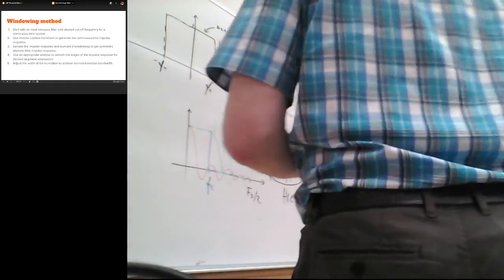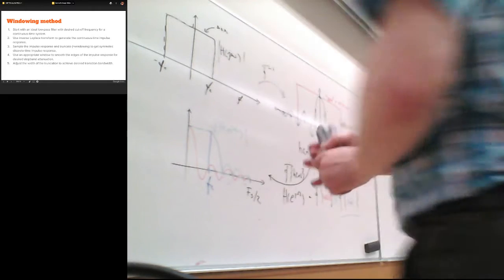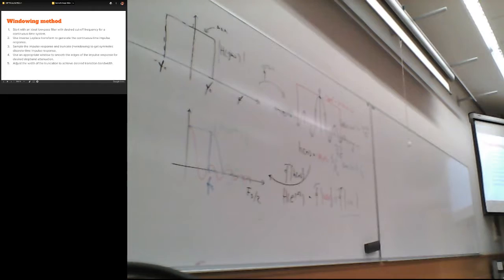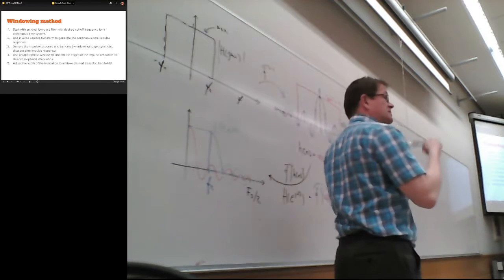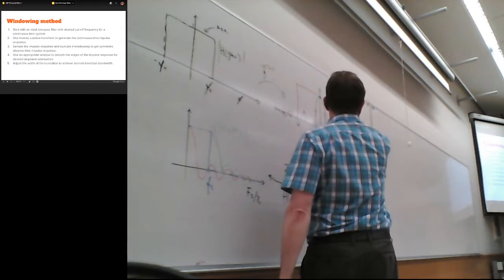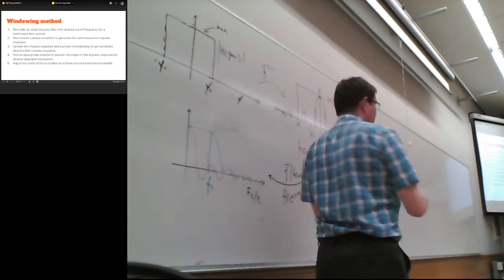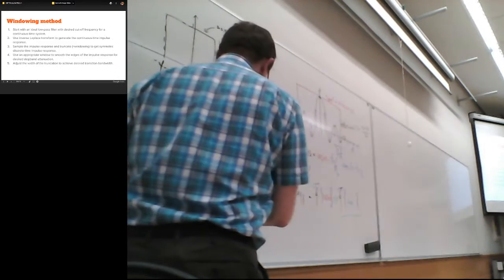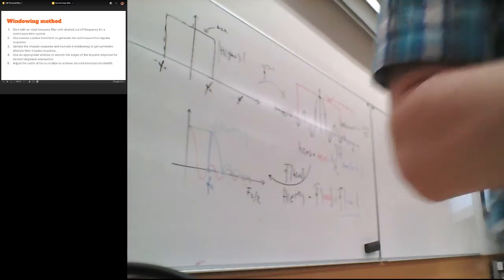Okay, good. But that's the start. We can actually next go and try if we get a proper control over the cutoff frequency. Since, yes, with this method, compared to, for example, the running average, which is a simple box window, we can actually control the cutoff frequency of the design.